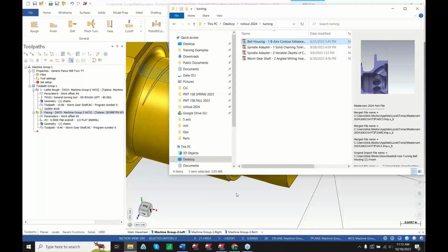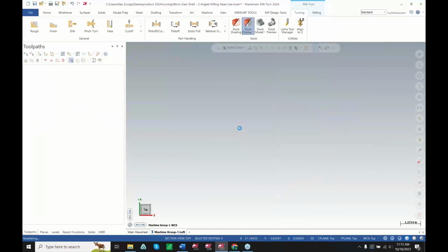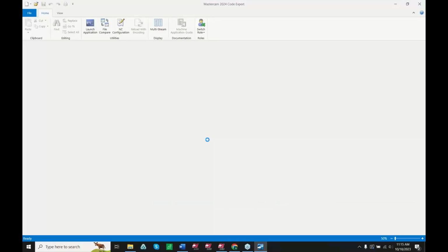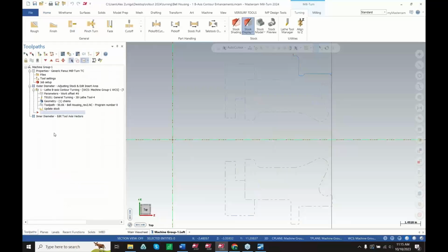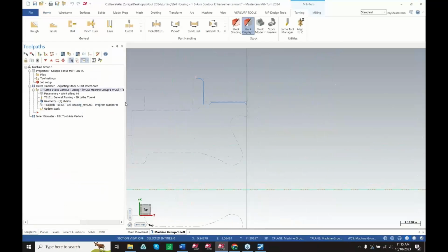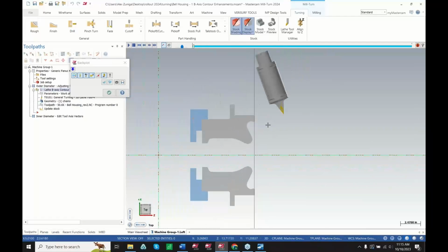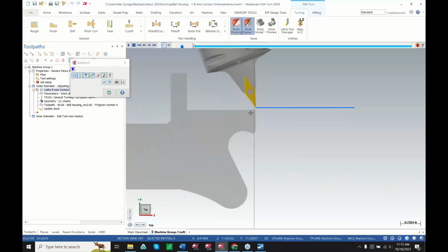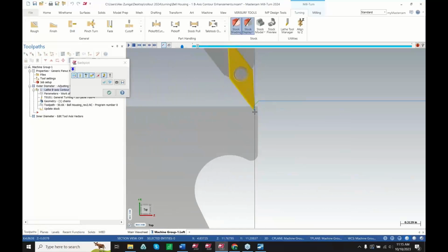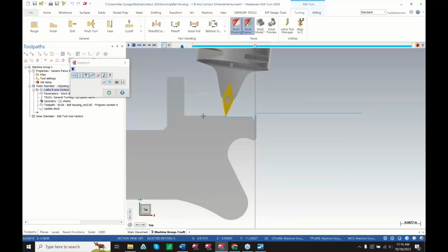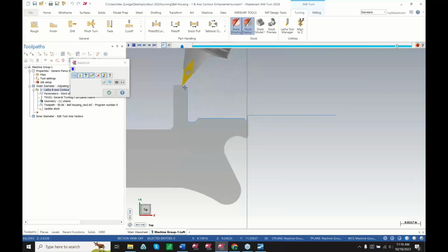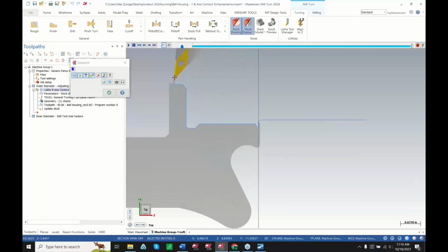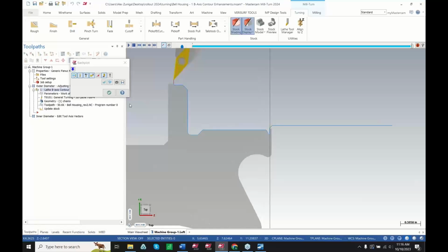The final enhancement that we're going to be talking about in the turning side of things is going to be the B-axis contour turning operations. Now when we watch this toolpath the way it's set up as is, we can see it starts at such a weird, odd angle. It wants to plunge in right there. Then it wants to walk up and over and kind of do its thing. Once it gets to about here, it's not too bad. Then it just walks straight up. But now we have some options in here to make the control a lot better than what it is at the moment.